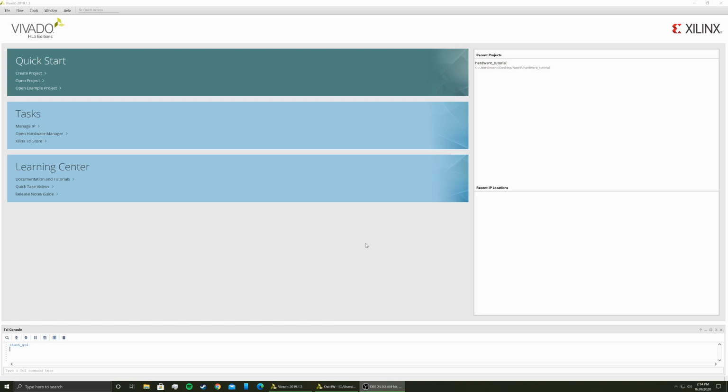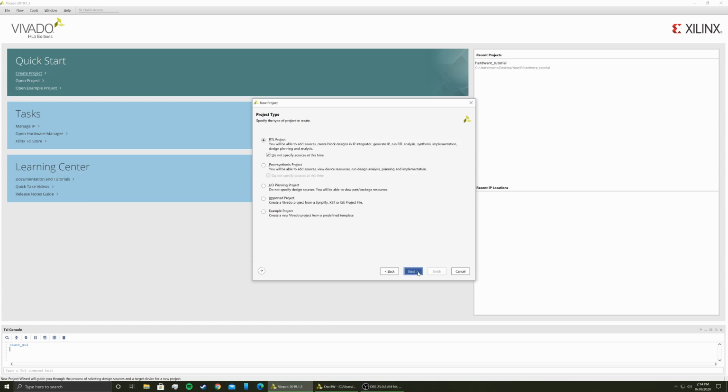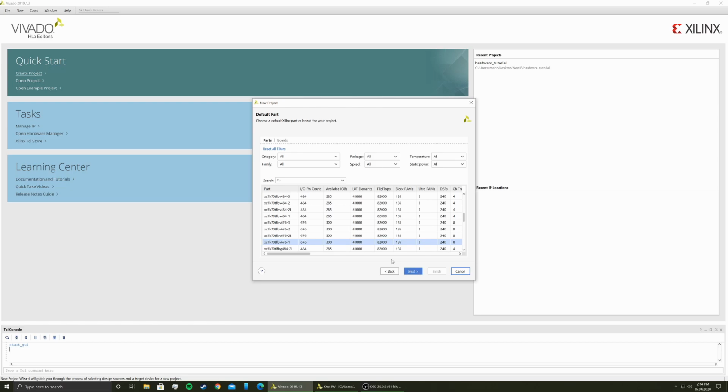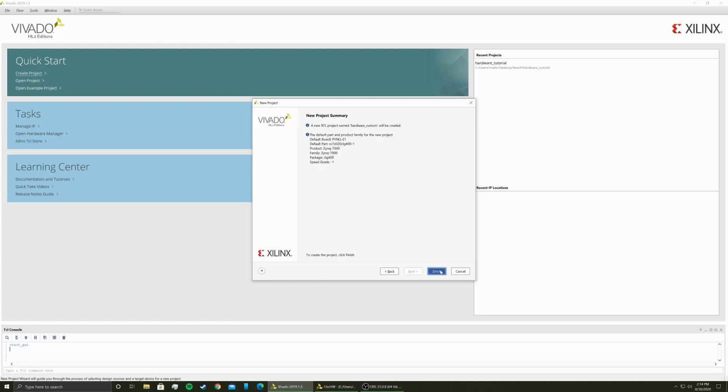So the first thing we're going to do is open up Vivado here and create a project. Once you have the project creator open, you can give it a project name. For the purpose of this video, we're just going to call it hardware_custom. You can change your directory, but we're not going to do that. I already know where it's going to go. And then you're just going to leave it as an RTL project. You're going to find the board that you want to work with. For me, I'm working with the PYNQ Z1 board, so we'll select that, and we will finish.